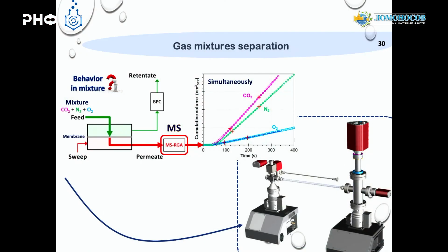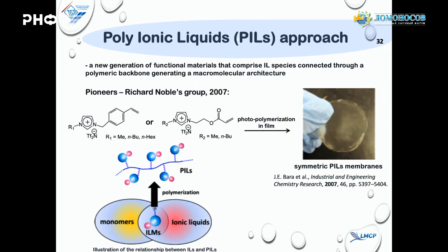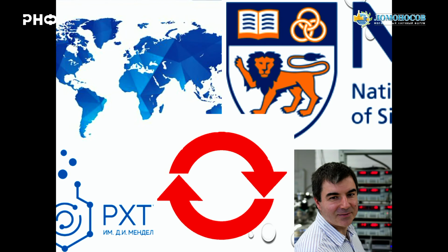And this is a kind of cooperation, but those two pieces of equipment are really interesting to analyze with, because they analyze really quickly different membranes and different gas mixture compositions. That means we can easily understand the kinetics of the separation process of the gas mixtures, which is really interesting from the fundamental or material science point of view, and also from the chemical engineering point of view, because you need to understand what happens inside your membrane, inside your module, or even inside your materials. But the Singapore equipment and the Moscow equipment work in the plug flow regime and the vacuum regime, and we are going to compare which is better and what the difference in results is.